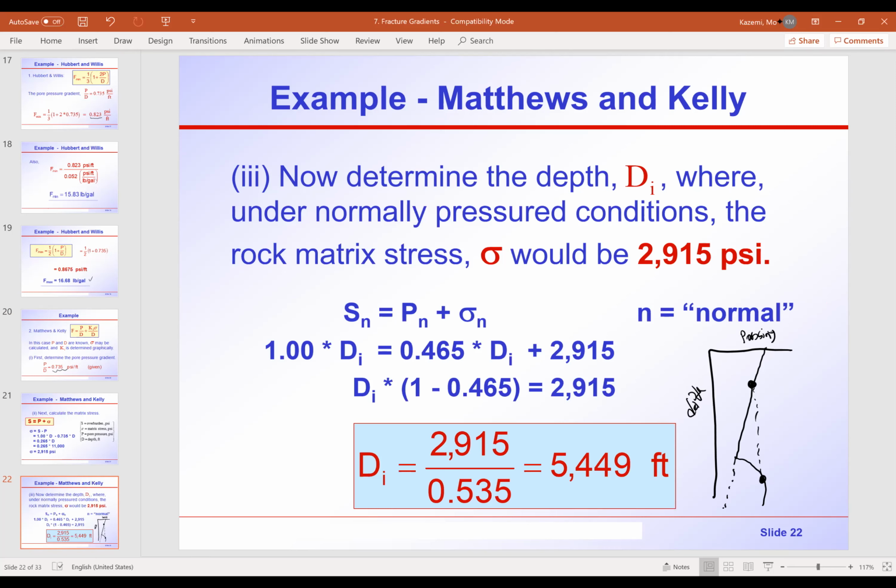If you have the same porosity value indicator, which can be determined by this vertical line, then the effective stress at these 2 points should be equal to each other. So what we do here in these calculations is to find these depths. We are at this point, and we want to find this depth, which is at the normal pressure gradient area.